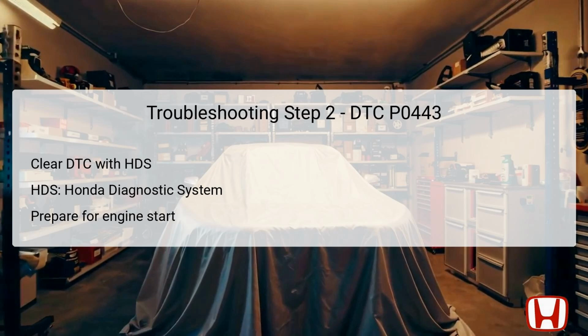After clearing the DTC, it's necessary to start the engine and hold the RPM at 3000 without load, meaning the vehicle should be in park or neutral. Holding the engine at this speed helps ensure the coolant temperature rises, activating the radiator fan, which is essential for proper engine functioning during diagnostics. This process cleans the slate and establishes a baseline for further testing.